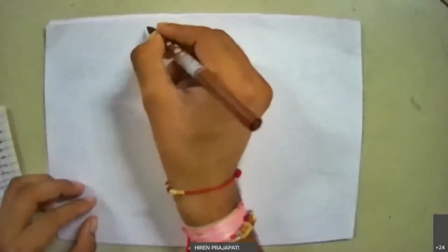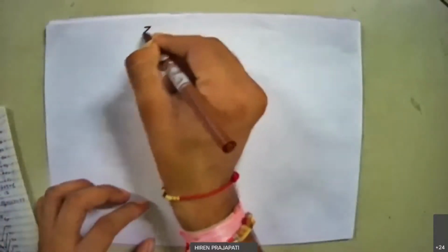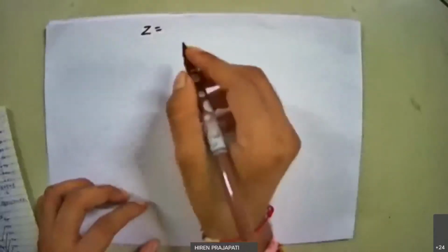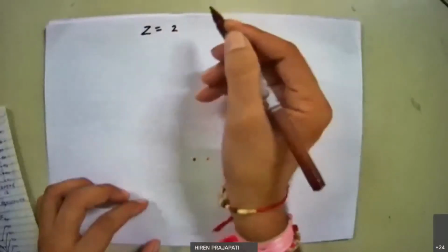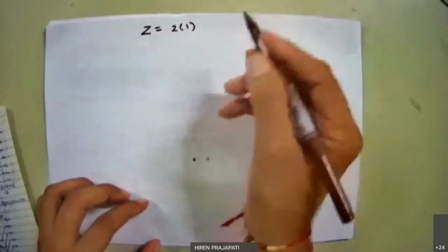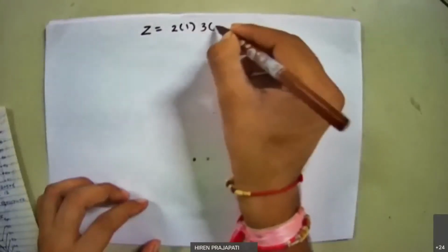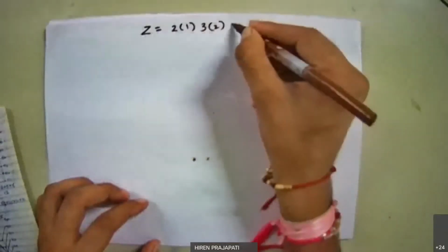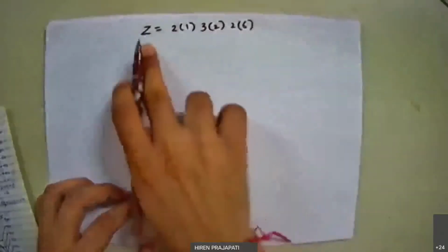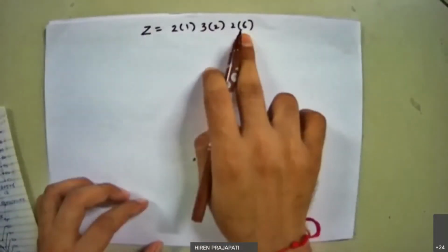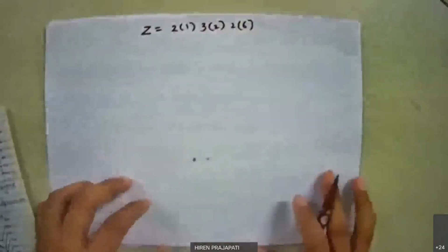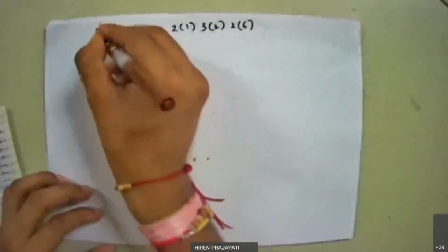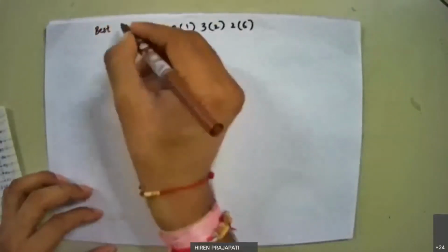So now, the ray diagram for 12 speeds, and I am selecting a base ray diagram, based structure equation as per the different criteria which we have discussed. I would say this is the universally accepted structure equation which fulfills all the requirements we have discussed so far. So I use only that base structure equation. This is the base structure equation for 12 speeds.